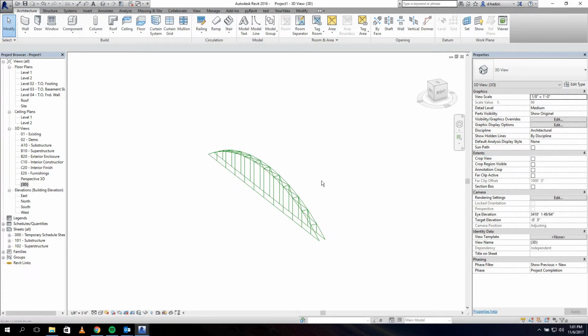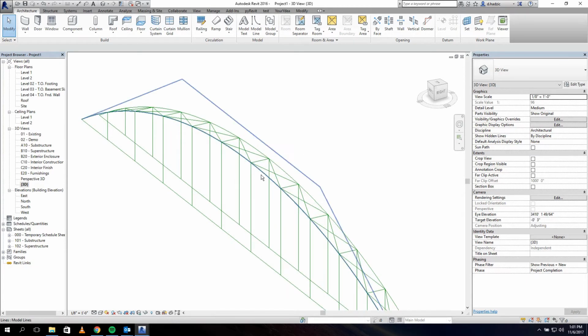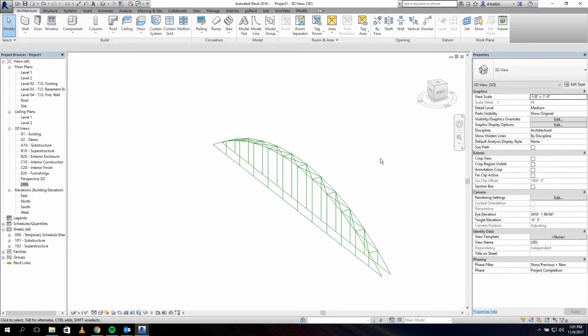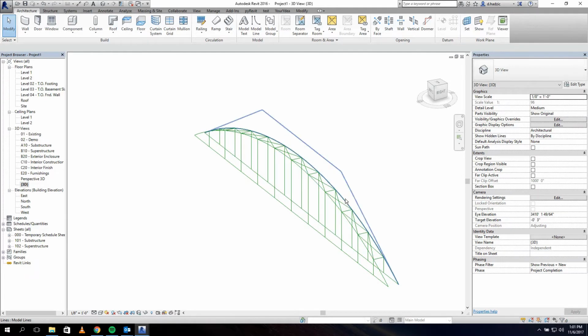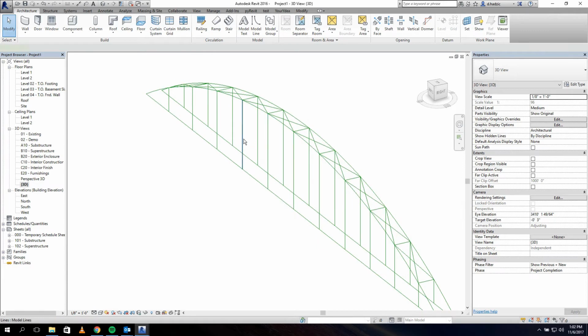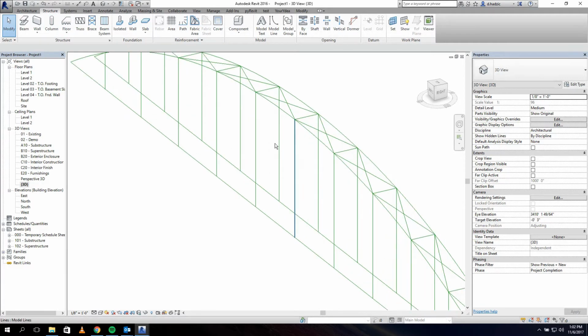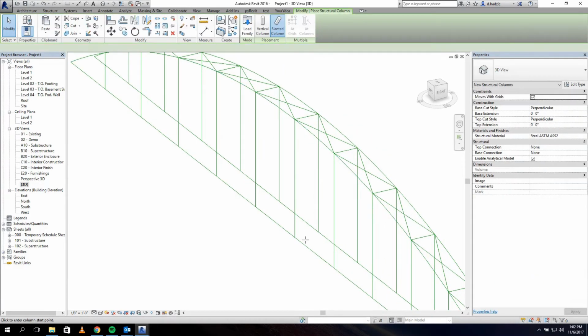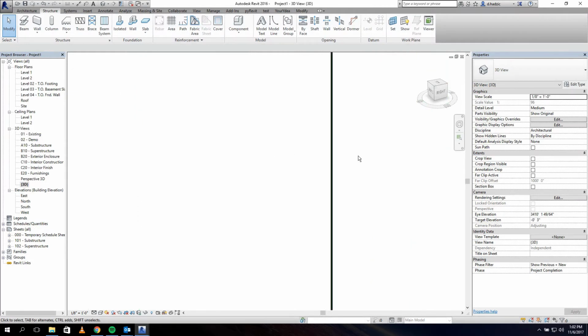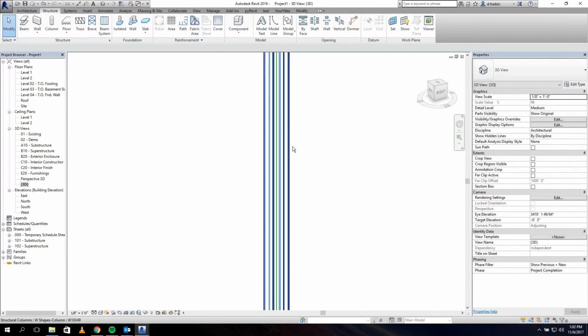In this tutorial we're going to create a bridge, and we're going to create a bridge from geometry. So in this tutorial we're going to use geometry to create, well, this bridge actually. And if you created the bridge, then you can fill in your lines with structures. So for example, I have my lines here, and now I can say, alright, I have a column from this point to here. I can fill in the whole bridge. You can see it's really small because it's a big bridge.